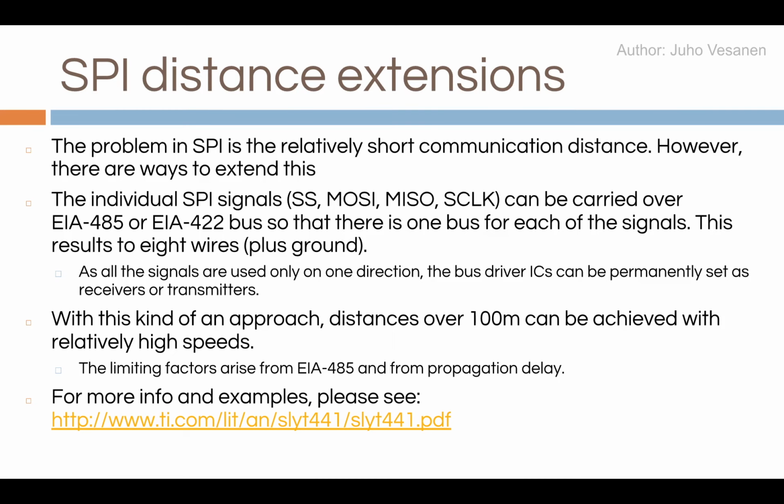Then you can have matched signals, and you can actually go over 100 meters. The only limiting factor is the propagation delay on the line. When it's very fast, you start having the clock and the signal coming back not in sync anymore. The writing is just fine, but reading data from a far away device might get tricky.